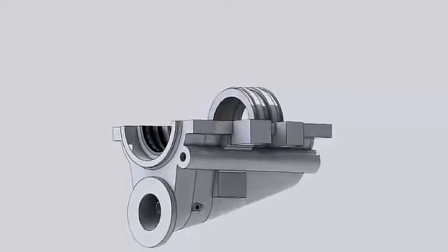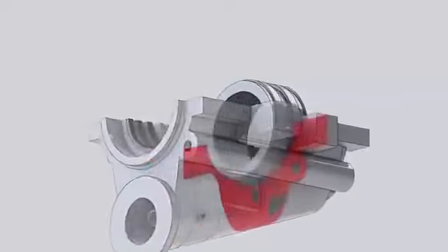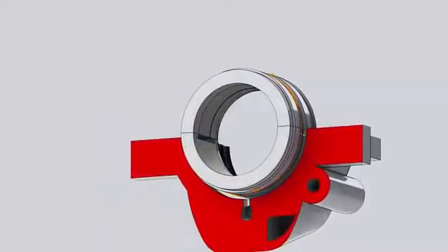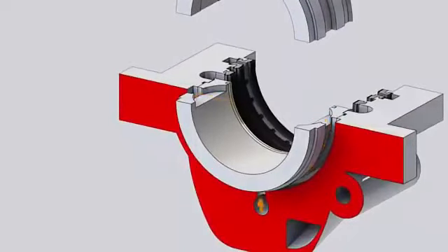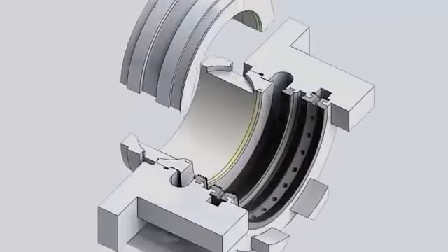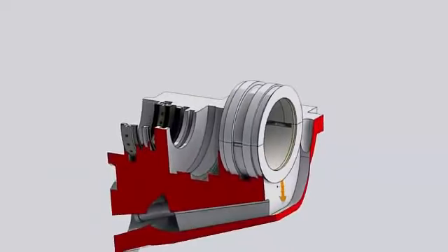For lubrication, oil is supplied through the oil feed pipe to a port in the lower bearing housing, where the oil fills an annular space around the liner and is admitted inside the liner through two grooves machined at the horizontal matching edge. Oil is drained through the vertical drain slot at the bottom of the lower liner half to the journal drain cavity down to the oil drain piping.